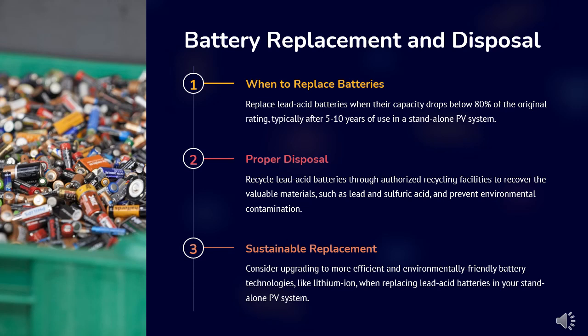Battery replacement and disposal. When to replace batteries, proper disposal, sustainable replacement. When to replace batteries: replace lead acid batteries when their capacity drops below 80% of the original rating, typically after 5 to 10 years of use in a stand-alone PV system.